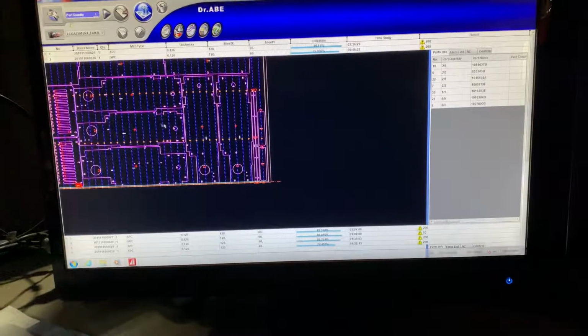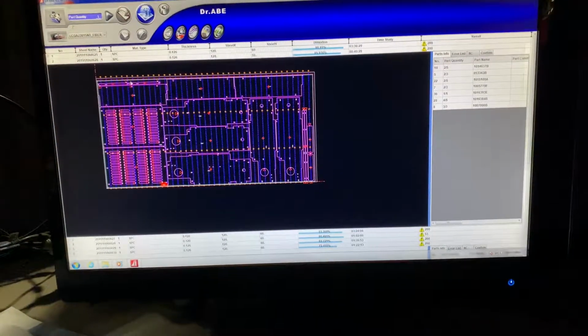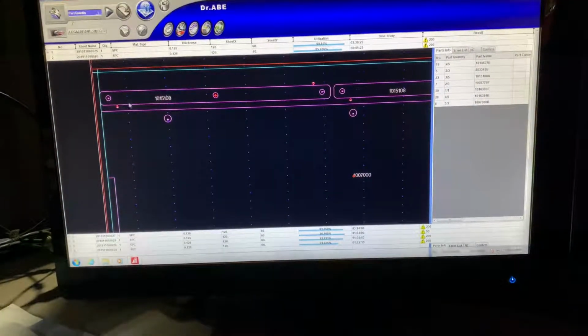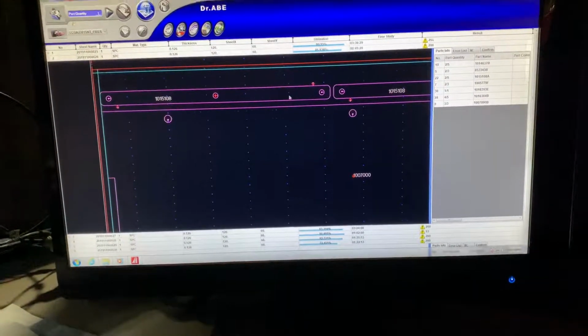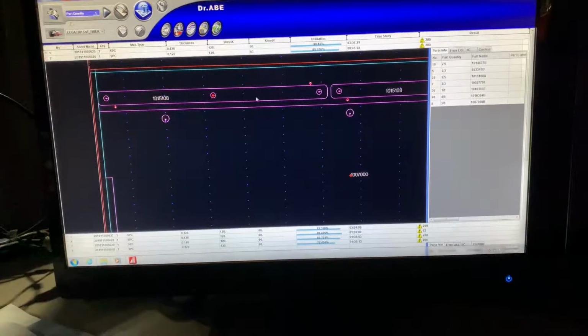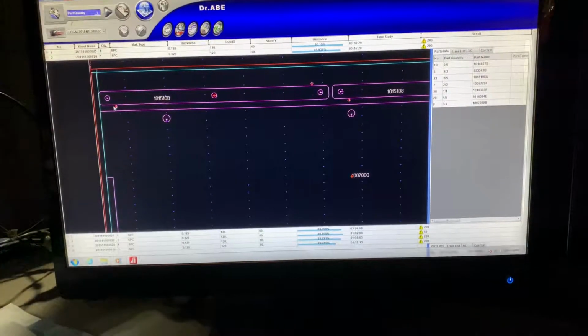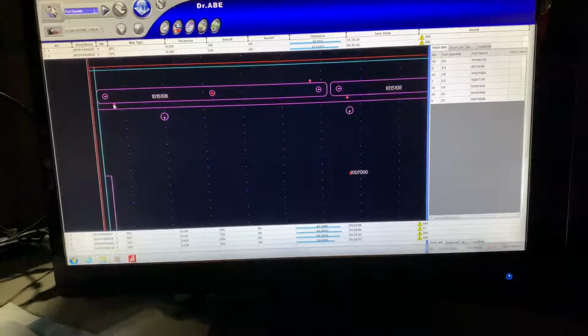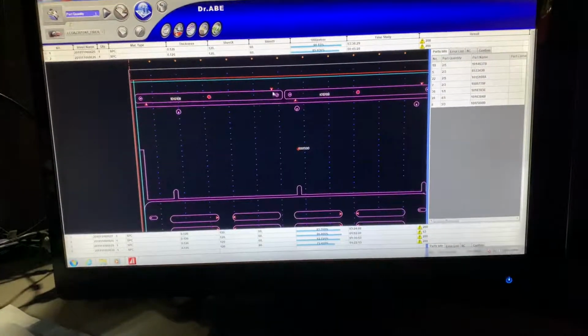But with DXF files, the software will automatically tell you if this part is going lengthwise on your x-axis and it's long enough to where it will not fall through the slats, it'll leave the tabs off. It won't tab it.